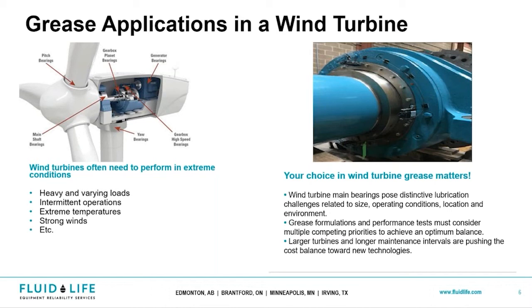And one thing I want to touch on as well is that your choice in grease matters, right? Not all grease is grease. There are different types of thickeners, different types of bases, different applications. Viscosity obviously is always going to be the pervasive thing in lubrication, and its flow rate and its change in conditions that affect it. Those things are just as valuable in grease as they are in oils, right? So making sure that that's consistent is a big deal, right?